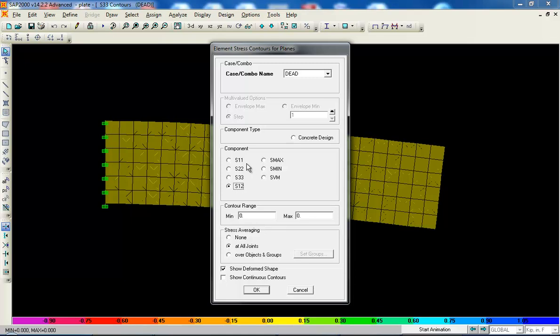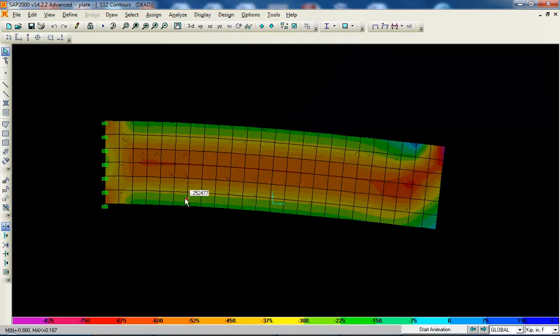Then this is shear stress, and you can see it's actually pretty nice. It's pretty small here, then goes up, and then it is maximum at the center, then it goes down. Remember what the shear stress distribution is in your classical beam theory? So this kind of imitated that, and you can see that from here to here, it's the same, because the shear force is the same. And there's some distortion here because of the local stress concentration again.